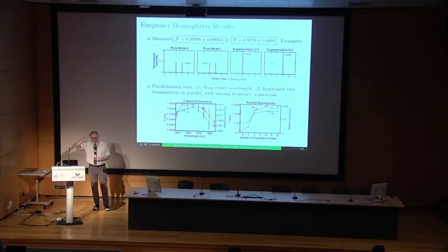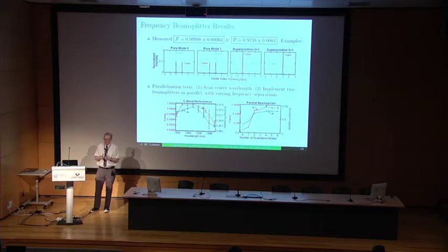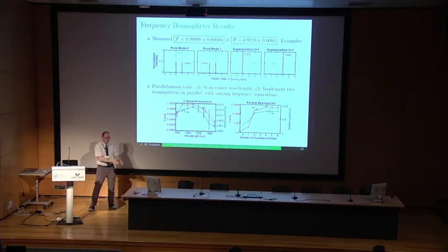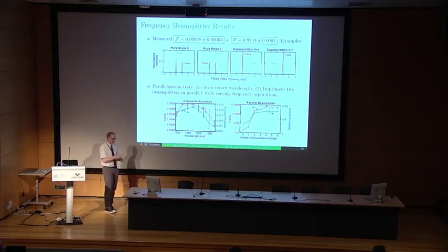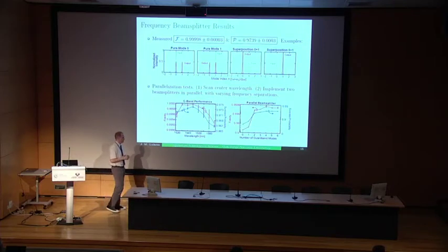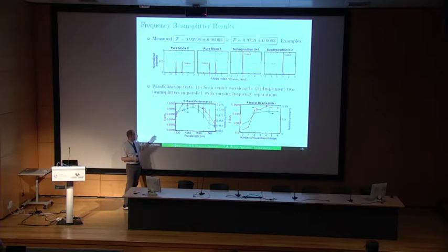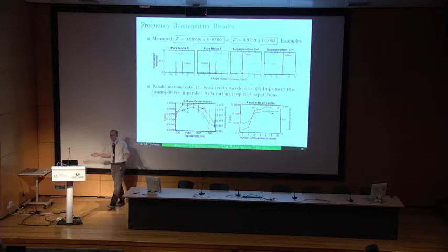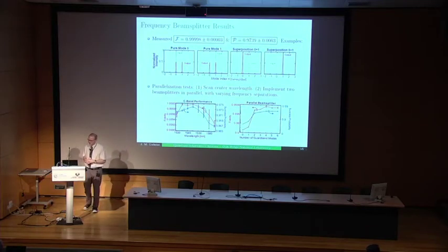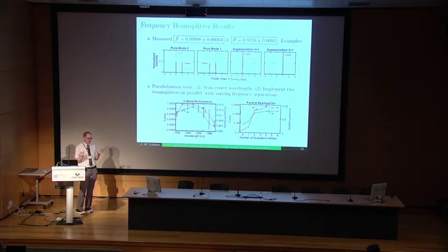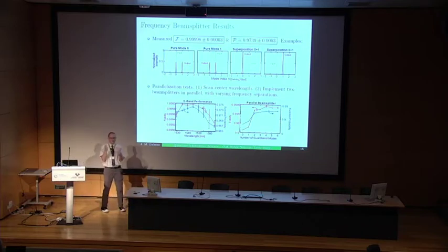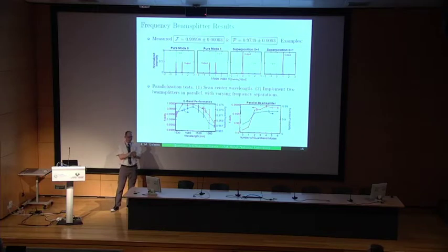And what's especially interesting, I think, about our operation is that it's readily parallelizable in that we can perform many of these gates in parallel in frequency space just by scanning the center frequency of the two modes that we're interested in. So you can see doing that actually explicitly, we find that we can maintain above 3 nines in fidelity and above 96% success probability over the entire communications band, 40 nanometers, around 1550 center wavelength. And we can also pack these very tightly and still have high performance. So if we put two beam splitters too close in frequency space, there'll be some crosstalk. But we found that if we put roughly 4 empty modes in between, we see essentially no degradation in performance. We can treat them as effectively isolated, and that's what the second plot shows.